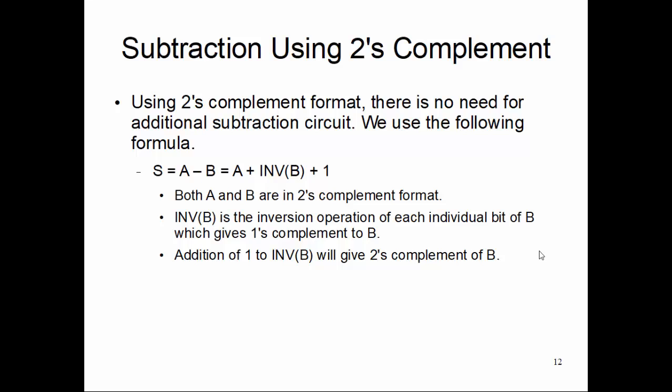Now all I need to do is to be able to represent the 15 or convert the 15 into a minus 15 pattern, right? So 5 minus 15 I want to do. So my two quantities were 5 and 15. All I need to do is convert this 15 into minus 15 and do addition. So how can we do that? Logically, it is very straightforward. You basically take inversion of the original pattern.